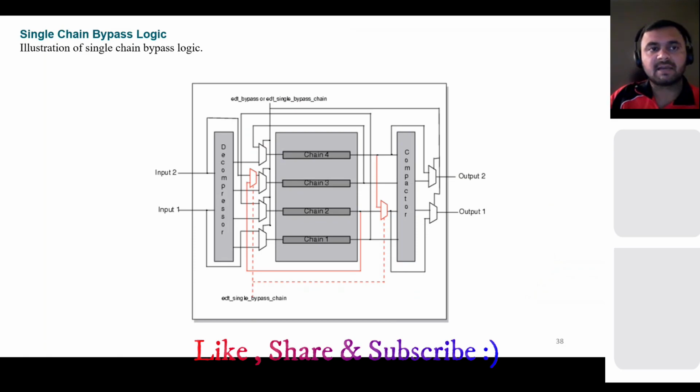Then you have a single chain bypass. Suppose you want to bypass a single chain, or 2 or 3 chains, depending on your design or on the error you are getting. Again you use the multiplexer on that particular chain output and just bypass it. The tool will not generate that chain, it will just skip it and generate patterns for the other chains.